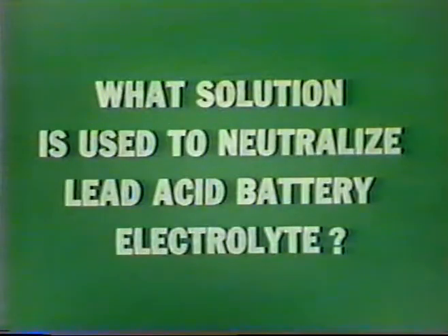Warning: when working around aircraft batteries, rings, metal watch bands, and neck chains should be removed, as they may inadvertently short across the battery potential and cause a severe burn. Question: what solution is used to neutralize lead-acid battery electrolyte?